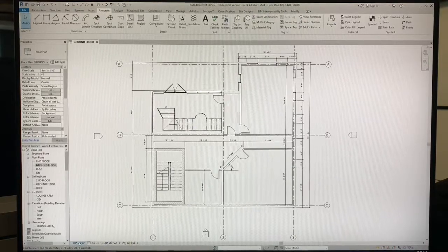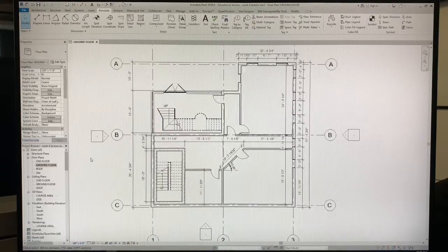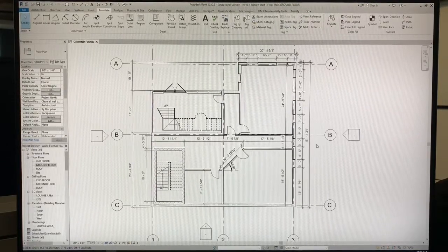So it's a shame to not set your annotation scale first, and then put in all your dimensioning, and then later on you realize, oh, my annotation scale was wrong, and when I put my dimensions down, they're actually up here on top of each other or hitting other things, because they're too big. So look, if you change your annotation scale, right now it's set at 1/4 inch. If you set it at 1/8, you see how much bigger my text is and all my other annotative objects. And when you're putting them down originally, you really didn't care about that because your annotation scale was at 1/4 and everything was small and it was doable.